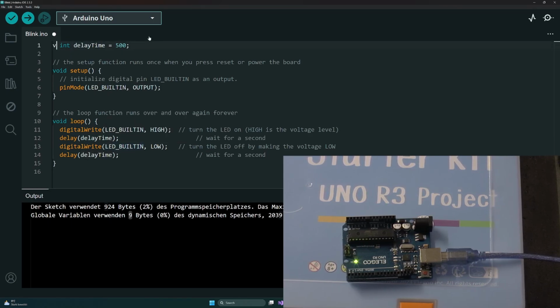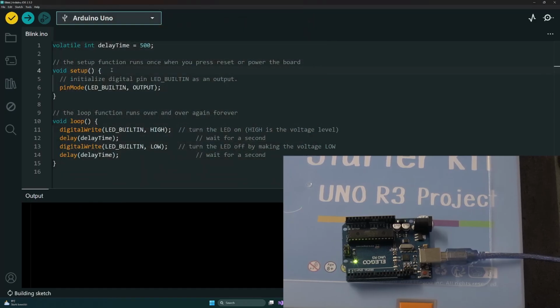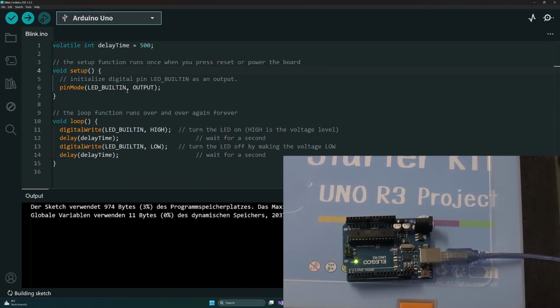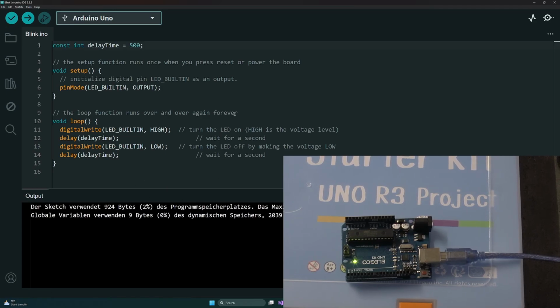Because I can actually lure the Arduino into thinking that this is used somewhere else. Now, just by changing the const keyword to volatile, you can see that we are using more bytes. And old compilers were not able to deduce this, maybe. So you can see now 11 bytes versus 9 bytes, just by changing a keyword, just changing a random word in our code.